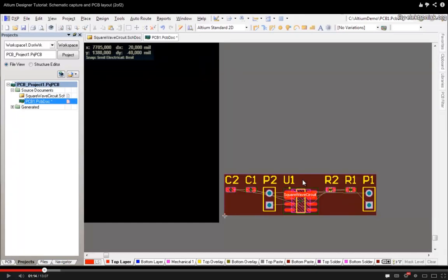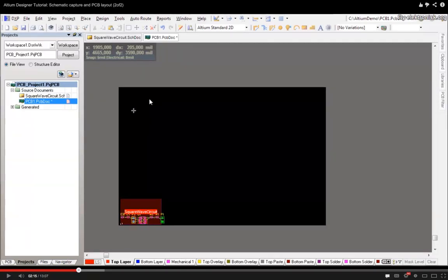in the PCB model. For example, these are headers. This is one of the components that you have, and these are the resistors and capacitors. The lines here are the wires according to your schematic file. These are just for you to wire them up more easily later on in the PCB file. After that, the black shape here is your board shape.